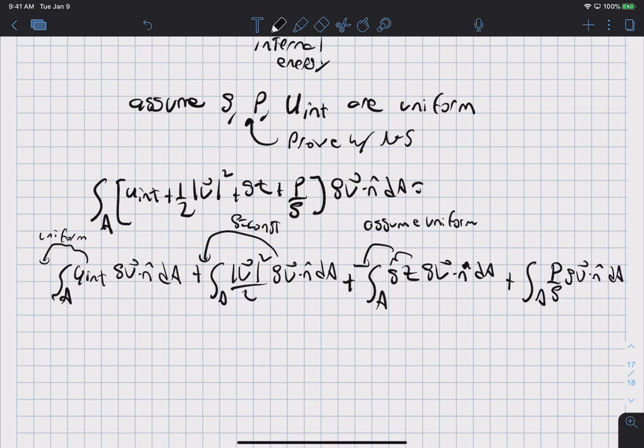You would need a truly gargantuanly sized pipe to account for the change of elevation across a tube. Maybe if you work with sewer systems, you might have to worry about that. But sewer systems are not pipe flow problems because sewers are partially full. They are almost never fully full. And these pressures cancel out here, and you can yank that out because that's also uniform.